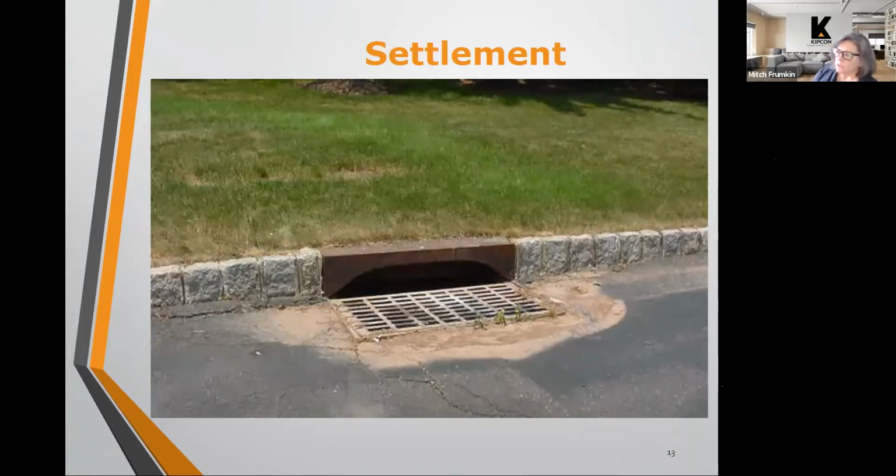larger debris, like cups and wrappers and branches and things like that, can clog the stormwater system, and it just keeps that debris out. A lot of the community roads are private, so you don't necessarily have to adhere to NJDOT standards, but we always specify that if you have these open heads, that they be replaced with the eco heads, because they do keep a lot of the debris out of your stormwater system